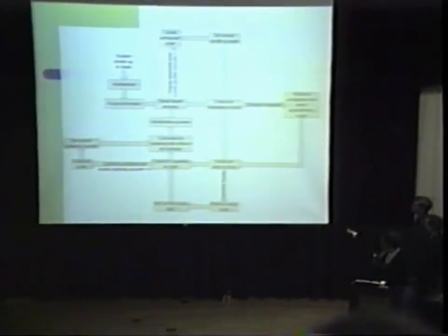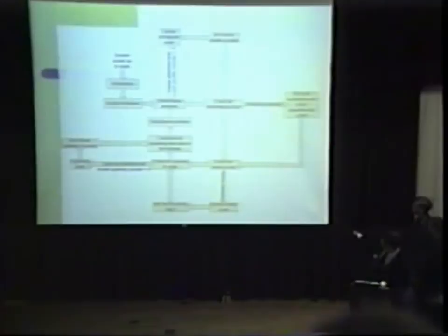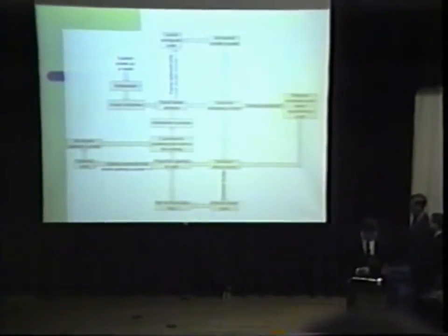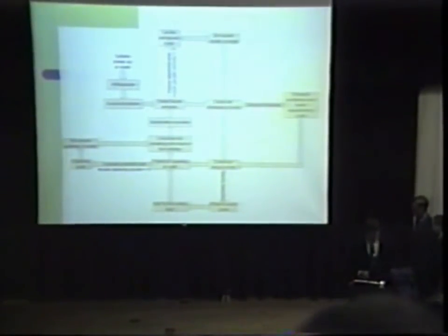Over here is the obstacle avoidance section of our code. Basically, if there was an obstacle in front of the robot, this code would try to reposition the robot so that it could go around the obstacle. If the robot encountered a wall directly in front of it, it would turn.